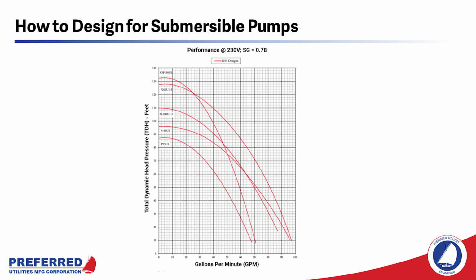If you have underground storage tanks that are deeply buried, positive displacement pumps may not be able to pull the oil out of deeply buried, large 12-foot diameter tanks. Also, you may have underground tanks out in a parking lot a long way from a building, and the engineer or the architect won't let you put positive displacement pumps near the tank. They don't want the eyesore of a pump set enclosure over their tanks.